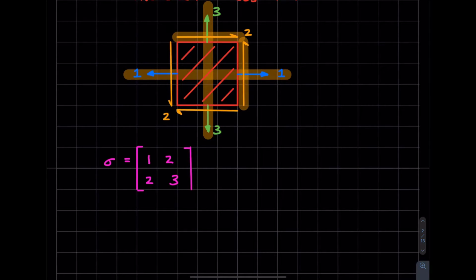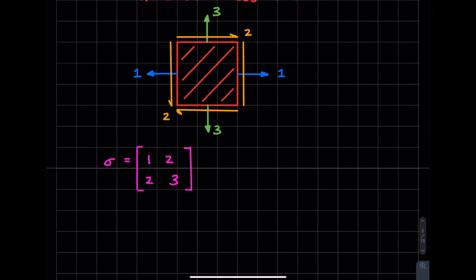So one thing the quiz doesn't tell you, but I do want to tell you, is kind of a secret. The arrows make a difference. You see how in this case my two normal stresses, sigma 1,1 and sigma 2,2, point away from the block. But what happens if they're pointing towards the block? Then we have to keep in mind that that 1 would actually be -1.